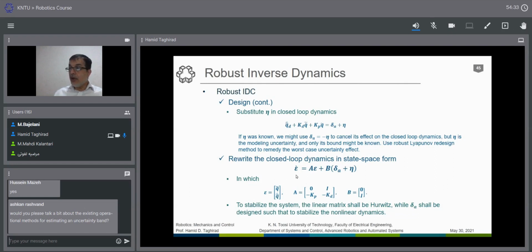So we consider the linear part and also the nonlinear part here. First, examine the linear part. This linear part shall be stable, and this A equation, as you see, is very simple. If this should be stable, all the eigenvalues of A should be negative, in the open left half plane, and then we can consider that to be stable.